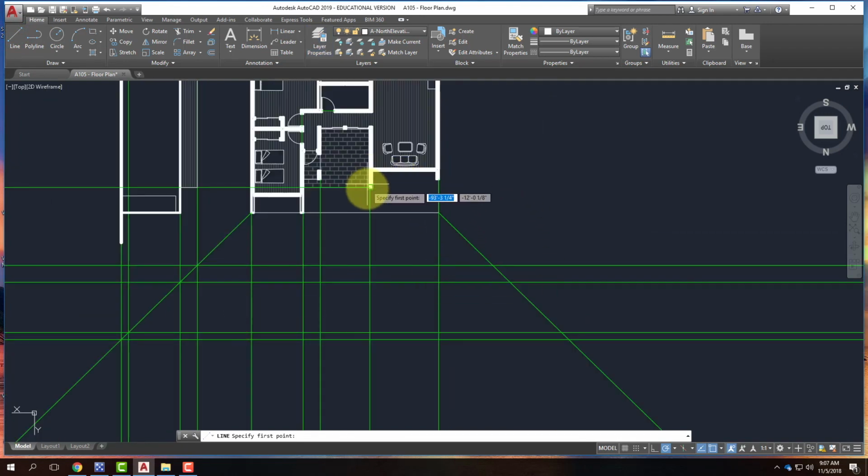So if I understand that this piece of the roof has a slope to it and a pitch, I need to understand what that slope is. And roofs are typically designated by rise over run. So when we talk about a 6 and 12 roof, it would be for every 6 inches of rise, you're going 12 inches of run. So you're going 12 inches over.